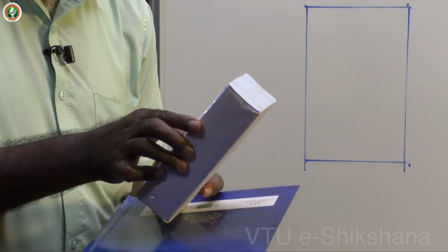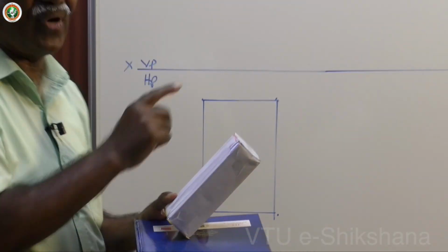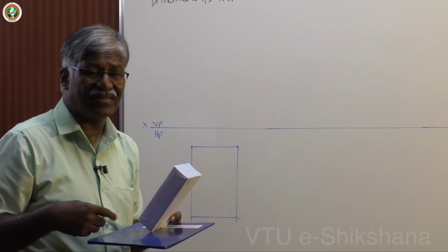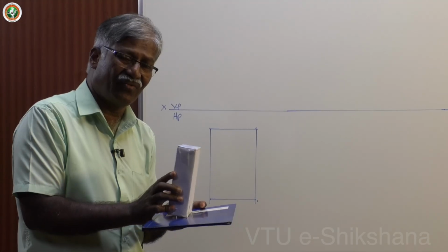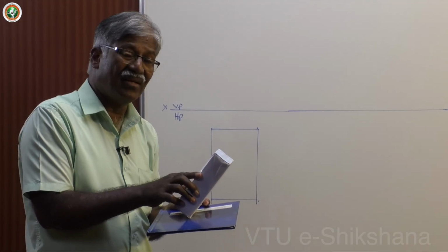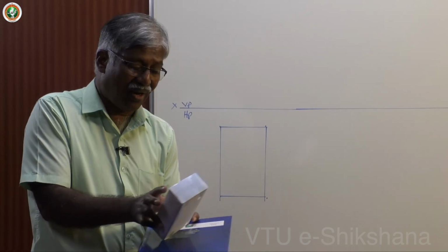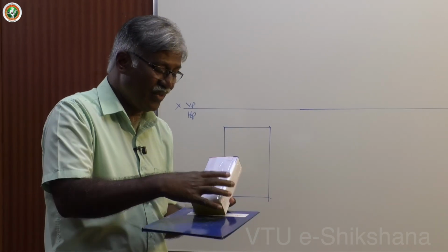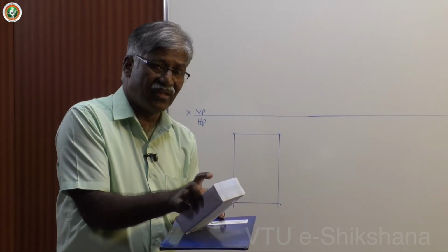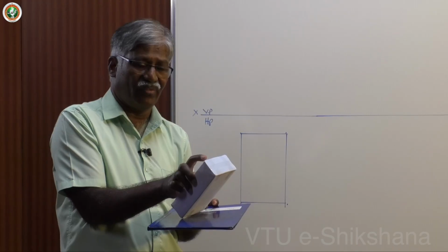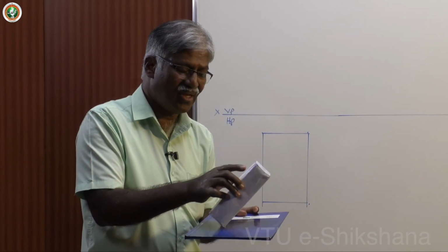Now after second position, what is asked? Draw the projections when the edge on HP is inclined at 45 degree. You know very well that longer base side is on HP. Now longer base side is perpendicular. We have intentionally kept it like that for giving rotation and taking only inclination to HP. Now you rotate like this. Now top face is nearer to the observer, or you rotate like this. By default, we do this. First position, second, third position. You can also do this, no problem. You can try that also. We will give information. Now I finally give first position, second position, third position.